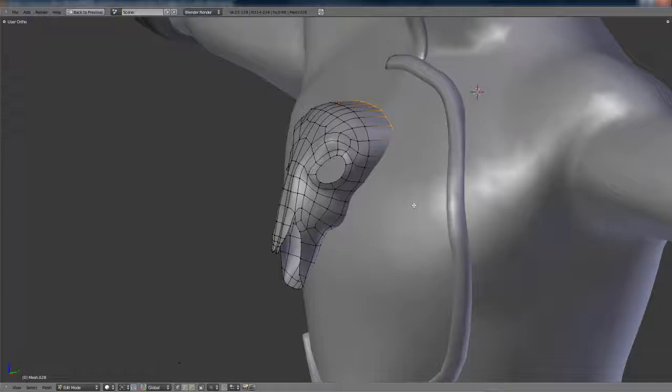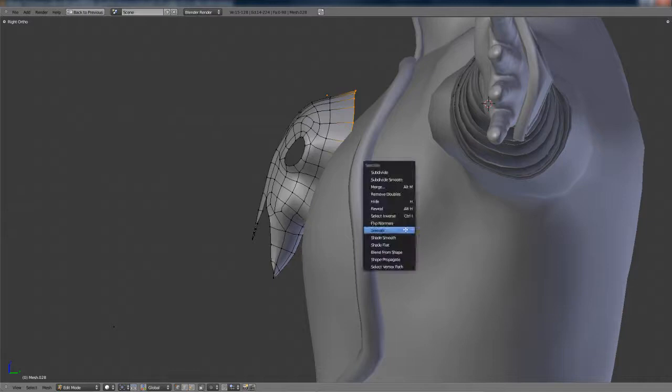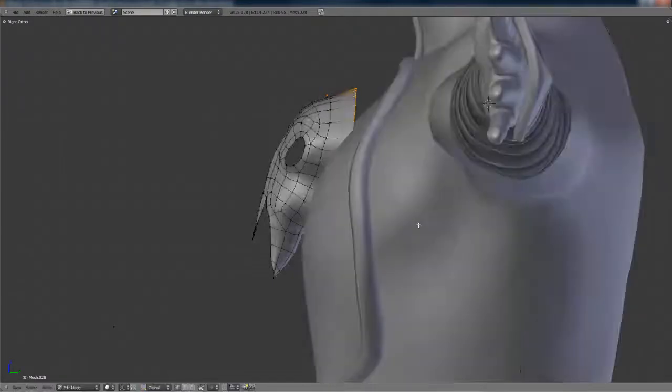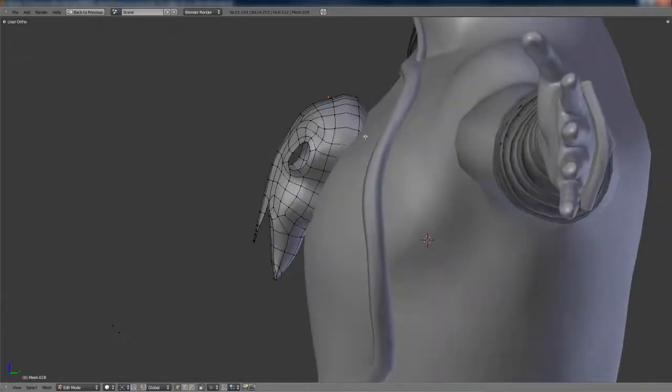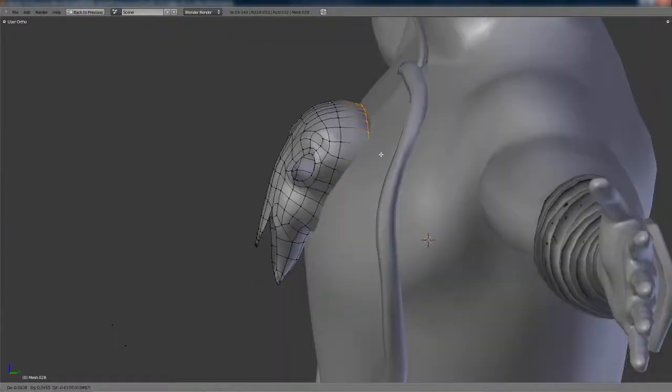You can see here I've selected all the vertices at the back top of the jaw and also the back of the head to form a ring, and I've just extruded them back once into the chest, and then extrude one more time and scale all those vertices down, and that will just completely lock off the whole back of the skull so that there isn't a huge gap.